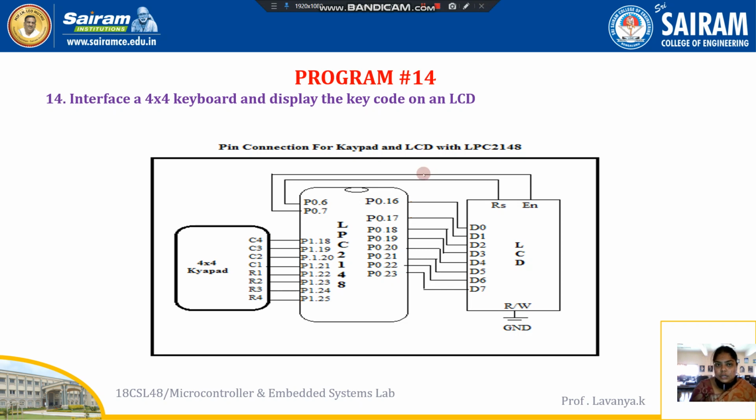One minute, I'll show this. I am going to use basically 2 ports, that is general purpose input output port 0 and GPIO port 1, slow interface. Our ARM controller works based on these 2 ports only. As per the program I have taken the port 1 address here. I am going to use port number 1, pin numbers 18, 19, 20, 21. I repeat, port number 1, pin numbers 18, 19, 20, 21.